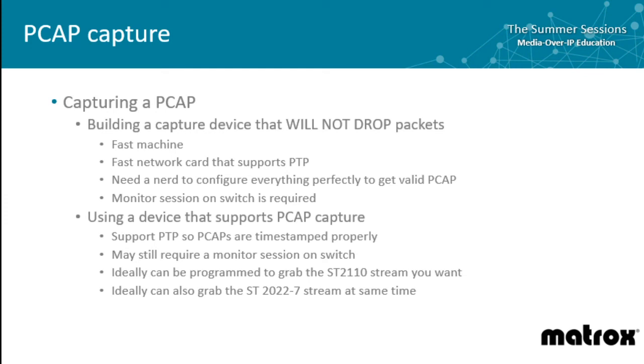Maybe you already have a device that does PCAP capture. Make sure it supports PTP, because the data needs to be timestamped properly. The device may require you to do a monitor session, although if you're lucky enough to have a piece of equipment that's ST 2110 aware and can also capture PCAP, it's probably going to just ask which stream you want to capture and be able to capture that.